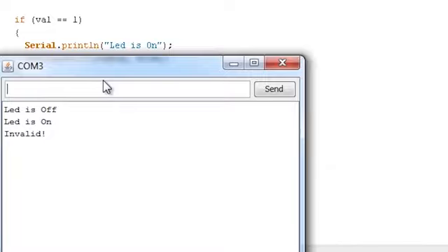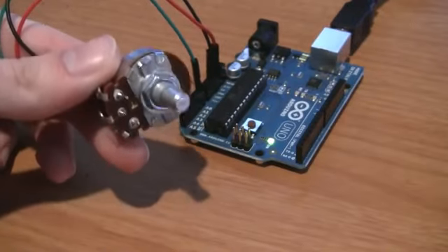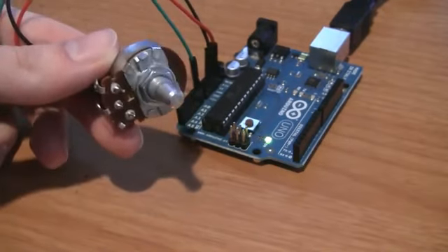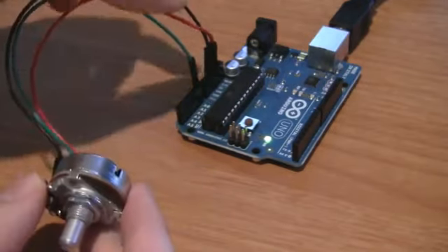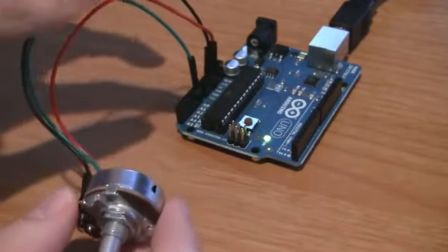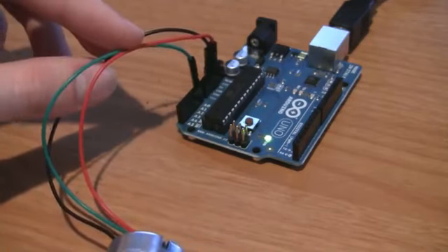We'll use the Arduino to control the computer. Here I have a simple 10K potentiometer hooked into the Arduino. Remember, we've used this one time before. You don't actually have to use a breadboard for this because we already have all the pins that we need. The red gets hooked into voltage, the black gets hooked into ground, and the green gets hooked into analog input 0.